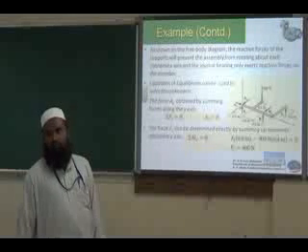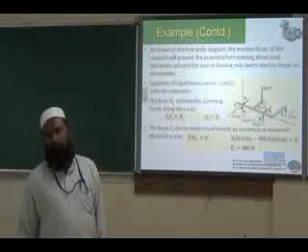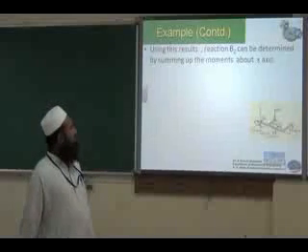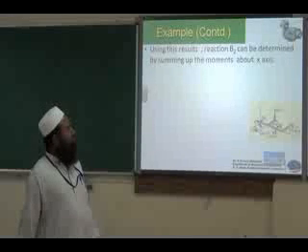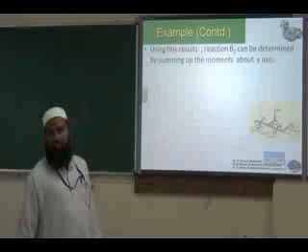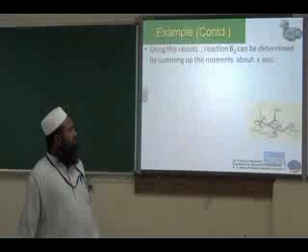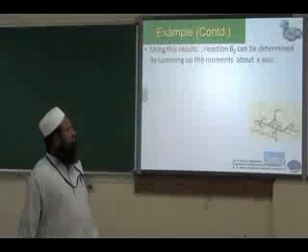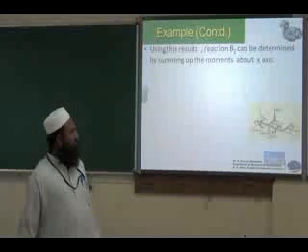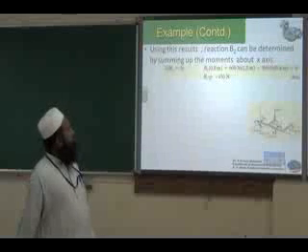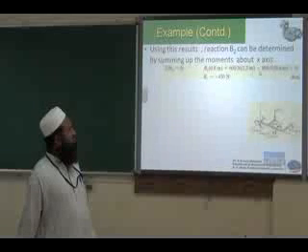Moment. X or Z? The summation we can take along X. Now in order to find Bz, we can take moment about x-axis. Bz is here. So to find the moment of Bz, we can take moment about x-axis. To find the moment of Bx, you can take x-axis or z-axis also. So I find first Bz by taking moment about x-axis.